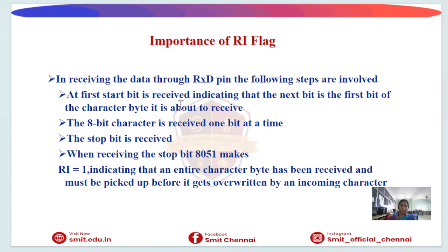What is the importance of the RI flag? This RI flag indicates the successful reception of a complete character. The microcontroller first detects the start bit and then receives the 8-bit character, one bit at a time. Finally, the stop bit is received. After receiving the stop bit, the 8051 automatically sets RI to 1. This indicates to the programmer that valid data is available in the SBUF register. The RI flag therefore helps the programmer know when the data reception is complete.